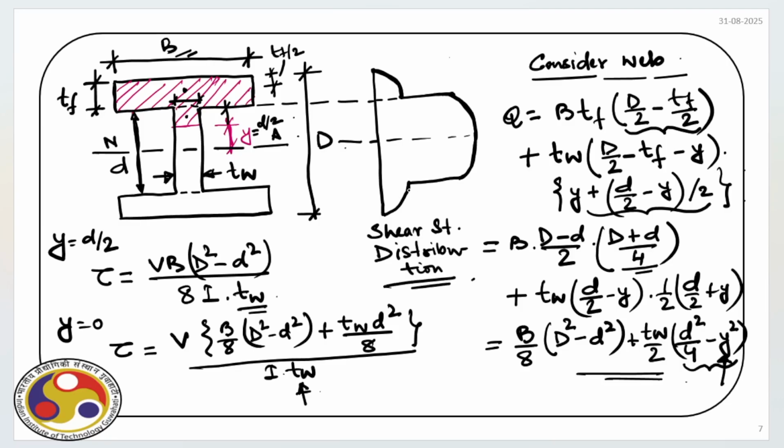So you can see if we quantify the shear force acting at a particular section, then based on the geometry we can draw the shear stress distribution over the cross section. And it heavily depends on the width over which we are going to evaluate the shear stress. As you can see, in the flange section, because we have a bigger width B, obviously the shear stress there is very small. The moment we come to the web, because we have a smaller section, obviously the shear stress will be more, so it is more here. So at this section, it is very critical.